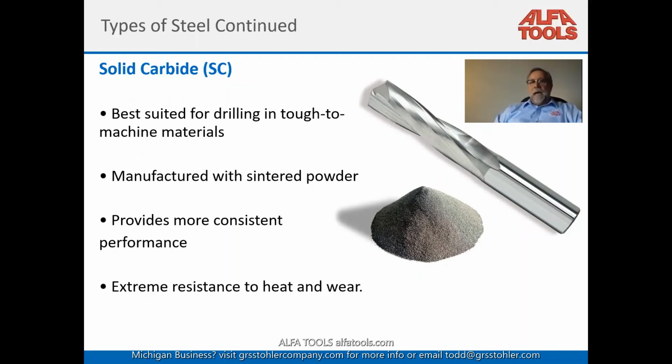So it's manufactured actually just from powders. They mix powders in. Everything is pressed down by, you know, hundreds of tons into blanks. Then it's sintered in a hip furnace. And then you have these rods that are almost as hard as diamond. And diamond wheels then grind the flutes and the points into them. Then you have a solid carbide drill.